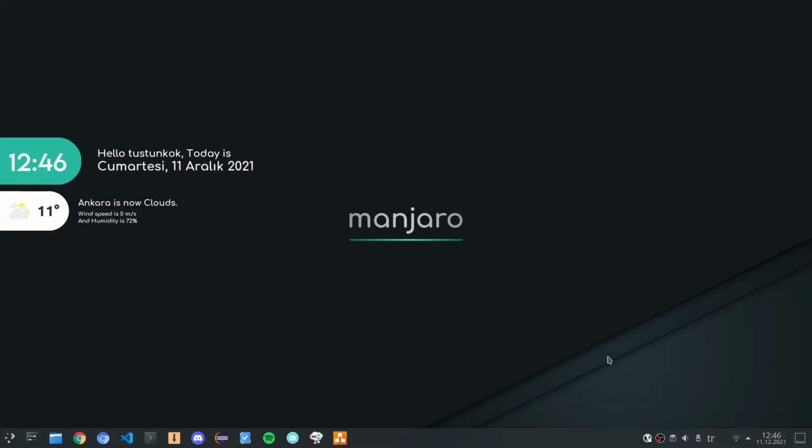In this example, we are going to simulate a full adder design. To do that, first we need to create a full adder module and a test bench. Both a full adder module and test bench are just files that include an entity and an architecture. While simulating the full adder, we are going to include the full adder design as a component inside the test bench.